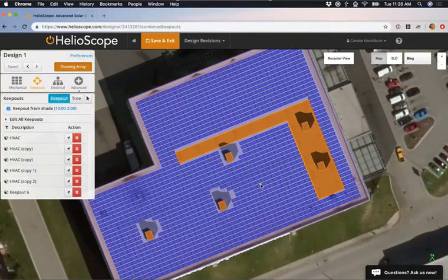First, if we were looking at the dimensions as we were designing, we noticed that we definitely need a north-south and east-west access path for this rooftop to be fire code compliant. And we've also got this long column of double modules right here and a few rows down here where maybe we want to put electrical equipment, and this isn't particularly friendly for ballasted racking. So let's just remove those as well.